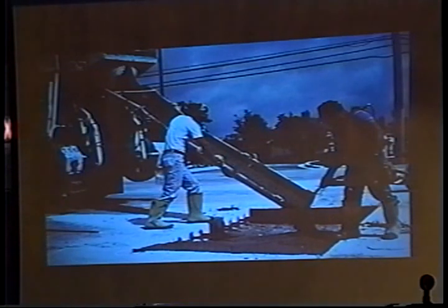You do have flexibility. In this location right here, there's an existing crack. That's not where you want to have a dowel bar. That should have been moved over. They should have spaced these things differently at that point. And you go in there and you fill it up with concrete and finish it off.